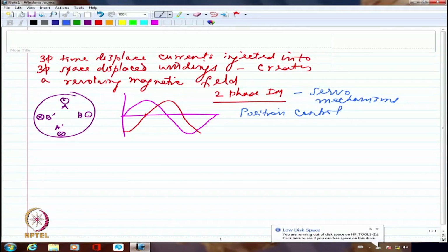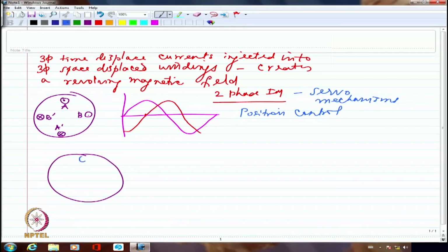a servo motor. One more point I have to mention before we move on further is, we told that the induction motor can be wound for 2-pole, 4-pole, 8-pole and so on. So if it is, for example, 4-pole, then what I will have is, if this is my stator, I will have basically, this is A and this will be A dash. And this will be A1, which is also corresponding to A phase, and this will be A1 dash.